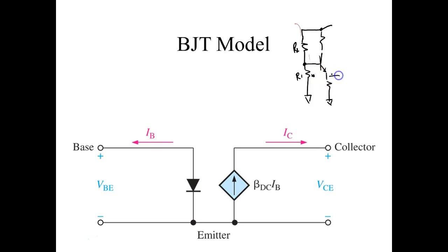Now, does that tell me the voltage drop right there? Well, this is going to be VB, so VE would be equal to VB minus 0.7. So if I've got 3 volts right there, right here I'd have 2.3 volts. If I know the size of that resistor, and I know the voltage drop across the resistor, what can I calculate? We calculate current.